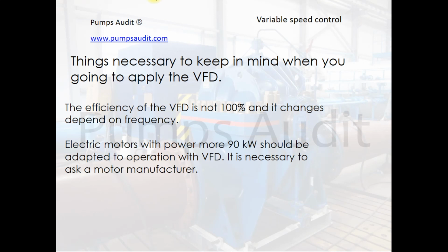For example, the efficiency of the variable frequency drives is not 100%, and it changes depending on frequency. Electric motors with power more than 90 kilowatts should be adapted to operation with variable frequency drives. It is necessary to ask a motor manufacturer.